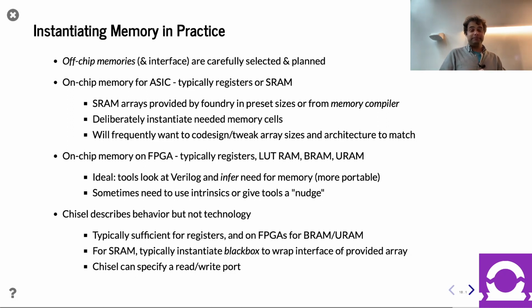And then finally, what does Chisel give you? Chisel is describing the functional cycle-level behavior. It's not actually a physical design tool, right? So in other words, you say Mem, and Mem by default gives a storage device with 0 cycles to read, 1 cycle to write. You can override the latency parameters, or you can use SyncReadMem to get 1 cycle read, 1 cycle write, etc. And on FPGAs, it actually works great.